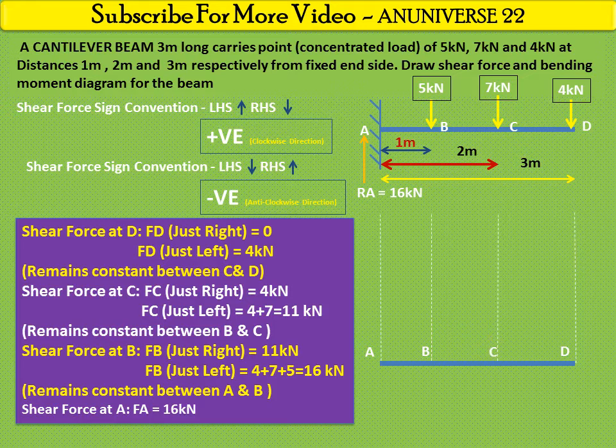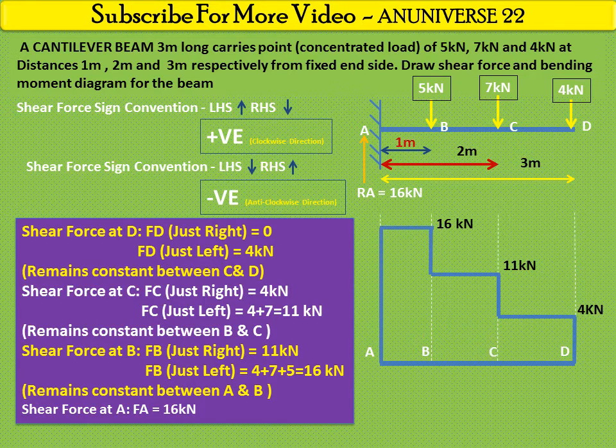Here we have 4 points A, B, C, D. At point D, shear force varies from 0 to 4 kN, and this remains constant between C and D. From C it varies from 4 to 11 kN, and this 11 kN remains constant between B and C. From B it varies from 11 to 16 kN, and this 16 kN remains constant up to point A. So this is the positive shear force diagram.